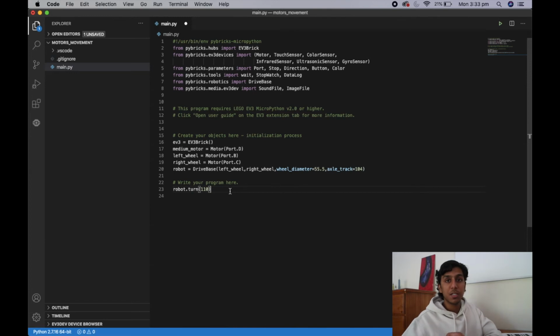As you can see, this was just a simple turn on the spot, and it was much more efficient and faster than the one wheel turn. This is why we're going to mainly be using robot.turn to actually turn. And as opposed to the run target command, this was a lot faster, and the run target command actually changed the position of the robot. The fact that this turns in its place means it is more mobile in a tight competition map.